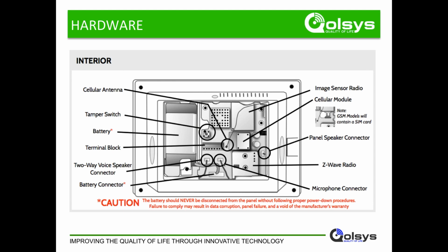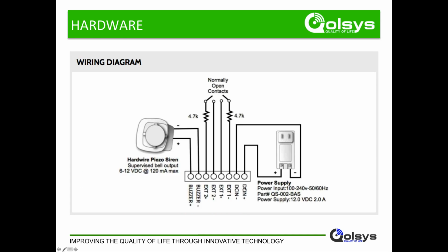Okay, so moving on to the terminal block. Now this was right in the middle here. I'll show it to you. Right here in the middle is this little terminal block. It's an 8-pin terminal block. This is where you wire the power. So you see DC in positive, DC in negative, and then again notice positive to positive, negative to negative here, and how that's wired.